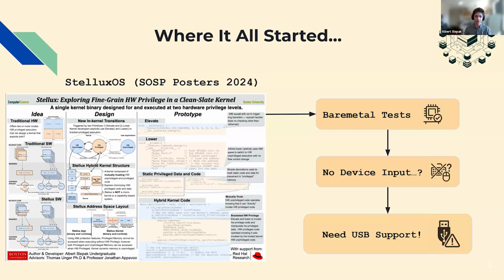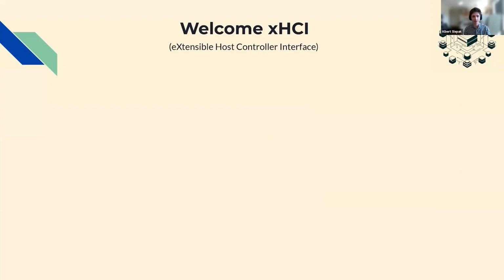I started Googling around looking for how to get started, where to approach this problem. And I learned about xHCI, the Extensible Host Controller Interface. It's a modern interface for the modern USB controller that can handle USB 2 and USB 3 devices, and it's been used in most modern hardware that's younger than about 15 years old. So I had the keywords.